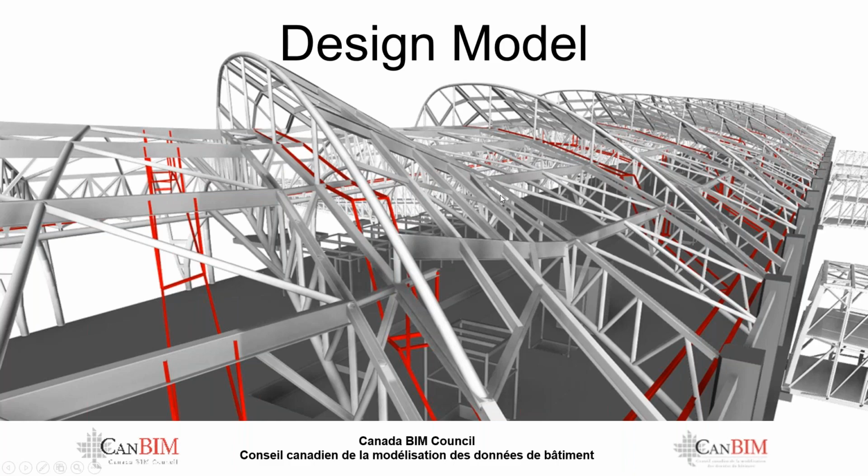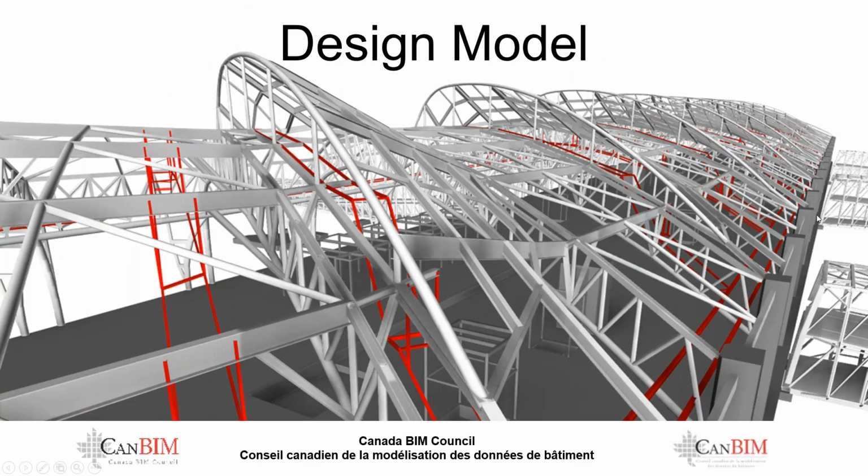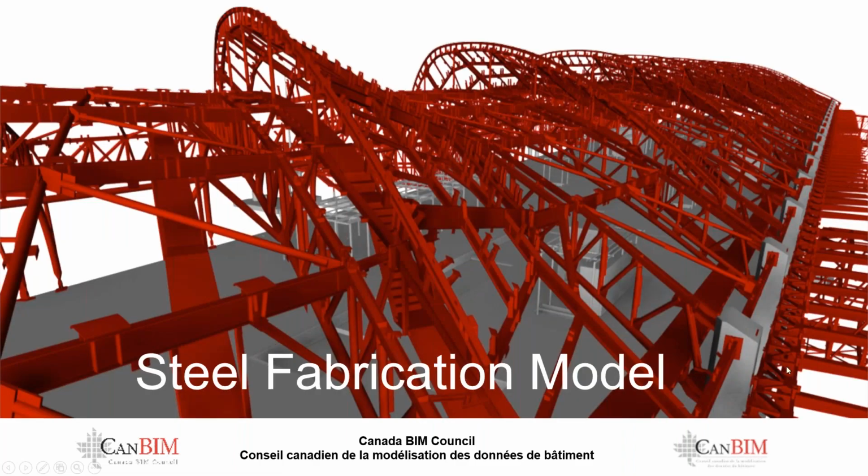That's the design model, and this is the fabrication model, pretty much taken from the same position. And there's a stark contrast and a stark difference. The biggest difference is all of the connections required for the actual roof systems, but also all of the secondary steelwork that was not in the design. So if I go back up one, you can see here, for example, along this elevation, there's a lot of steel that wasn't modeled at the design stage. It's considered secondary steel. And when you model it in, there's quite a lot of steel work involved.